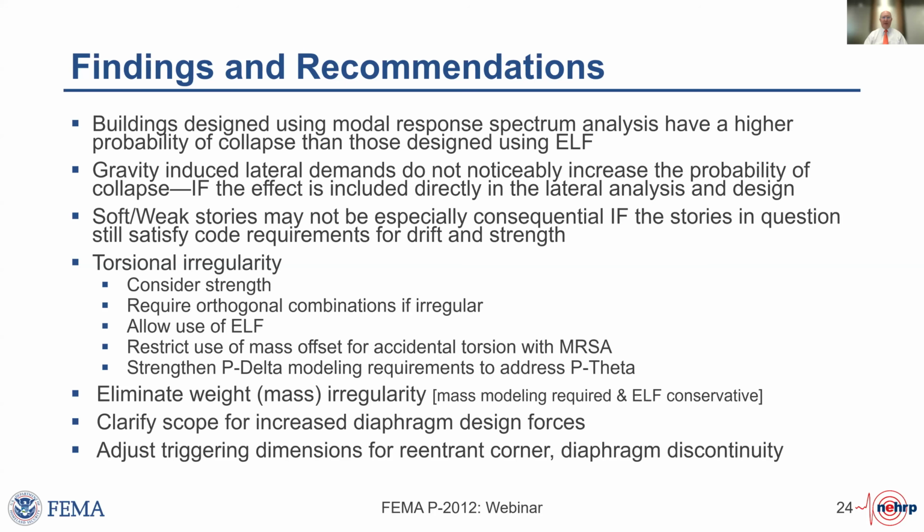Because the ELF method is more conservative than modal response spectrum analysis, we found that we could allow the use of ELF. It didn't need to be prohibited. And in fact, with modal response spectrum analysis, there are some options that you could use that would actually cause problems in your assessment of accidental torsion. We'll talk about that, but the project found that.